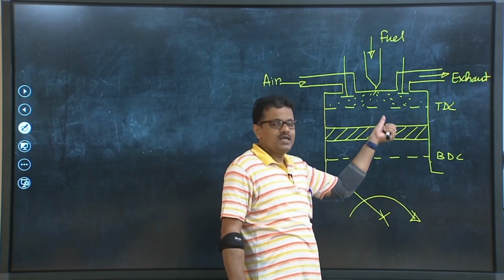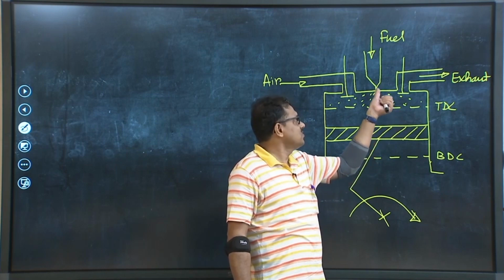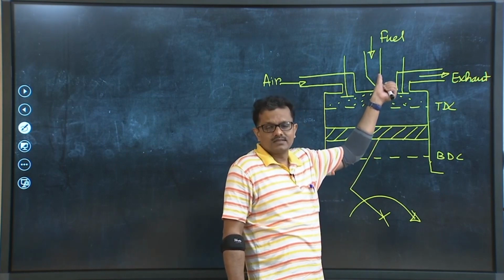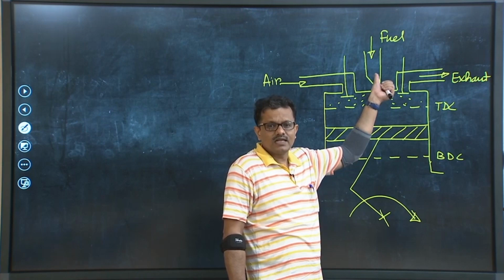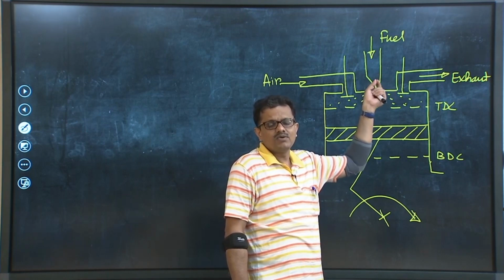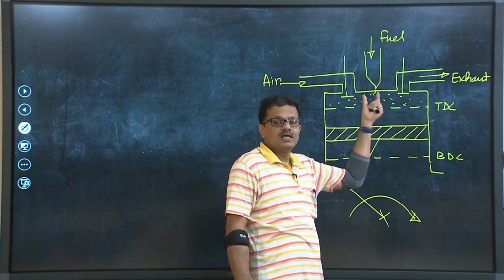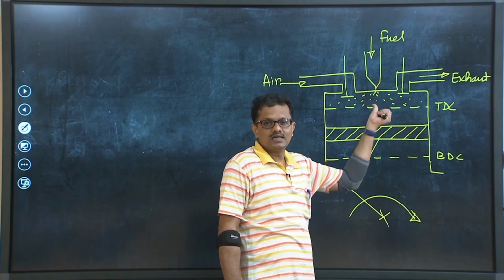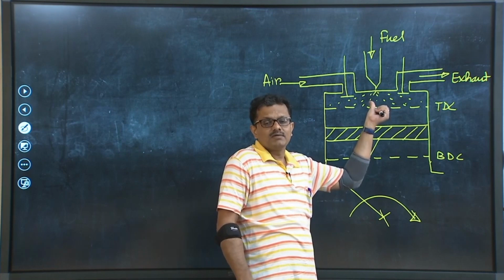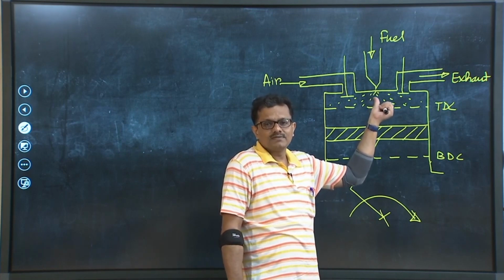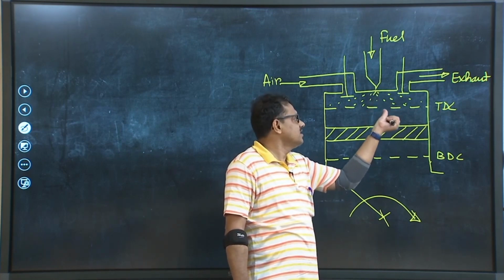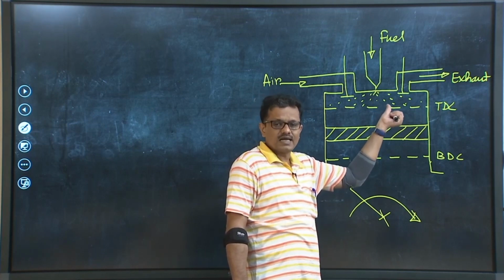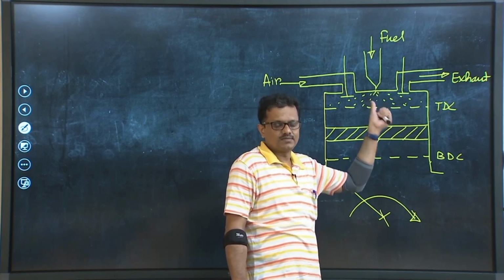Also, the nozzle is a mechanical device, so it needs a finite amount of time to spray a certain amount of fuel per cycle into the engine cylinder. During that time, it is very unlikely that the piston will remain exactly at TDC and the volume will remain constant.